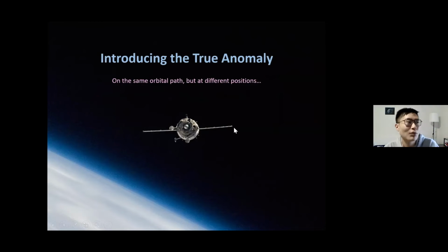These tilts, for people who are coming from aerospace robotics backgrounds, are known as the 313 Euler angles. It's a bit similar. Euler angles are like your yaw, pitch, and roll. So it's the same as taking an object and doing a yaw, pitch, and roll. In this case, for a 313 rotation, it's a roll, yaw, roll, right? And then it still gives you the same degrees of freedom you need to specify an object in 3 degrees of translational position and 3 degrees in rotational position.